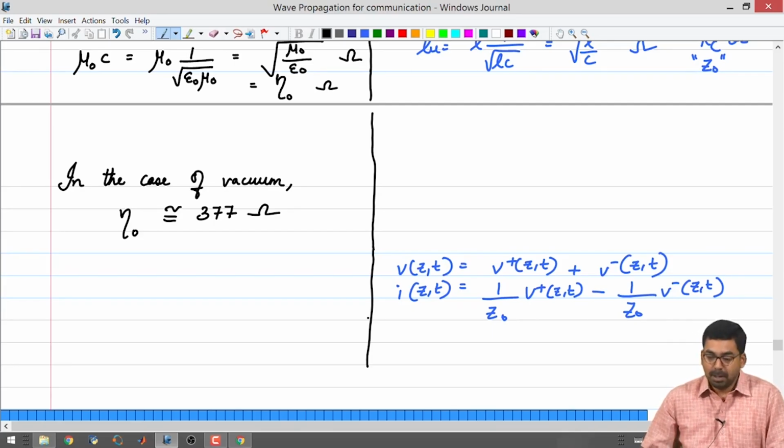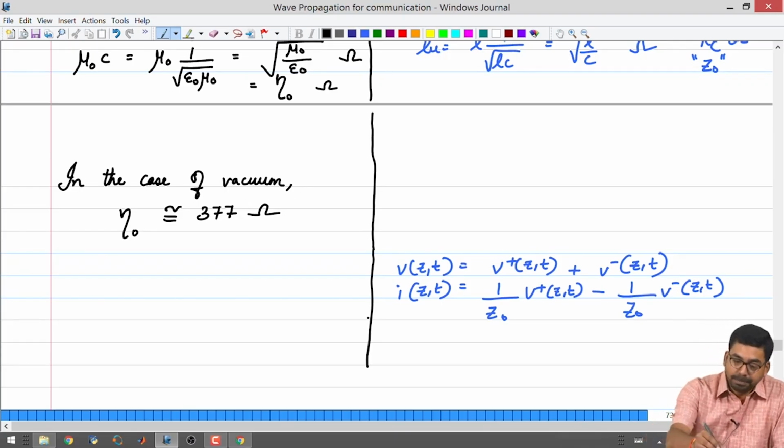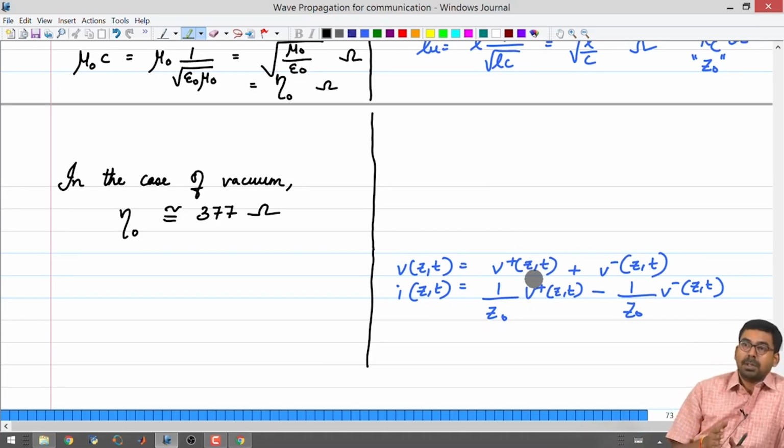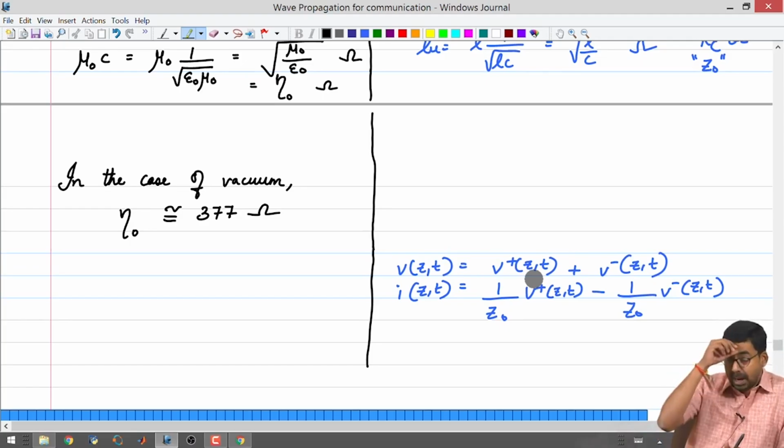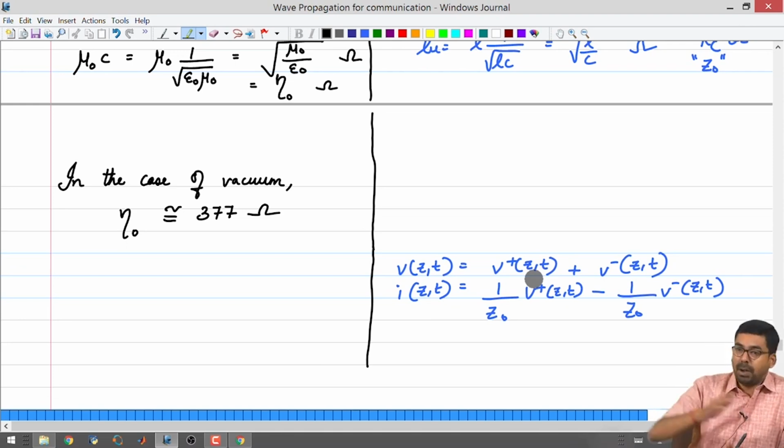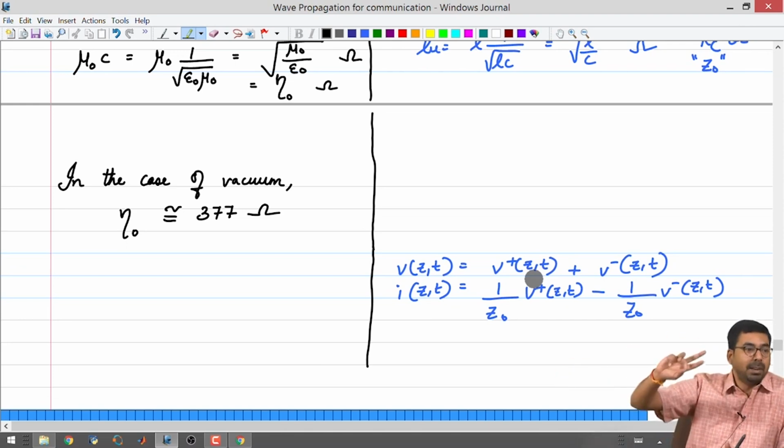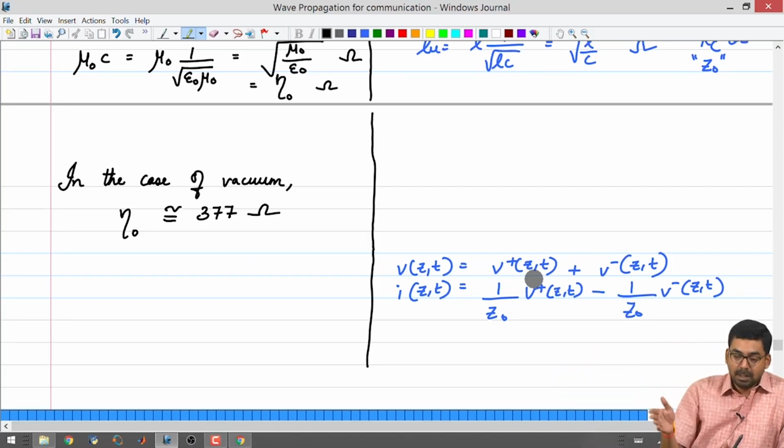But you can be sure that in the case of transmission lines, one of the uses of the bounce diagram was, suppose you had an abnormal termination of your transmission line somewhere, you can expect a reflection or a bounce, and from there you can figure out from the time of flight of the pulse how far away it is, and depending on the sign of the voltage, whether it is a short circuit, open circuit, etc. The same thing can be done here also.